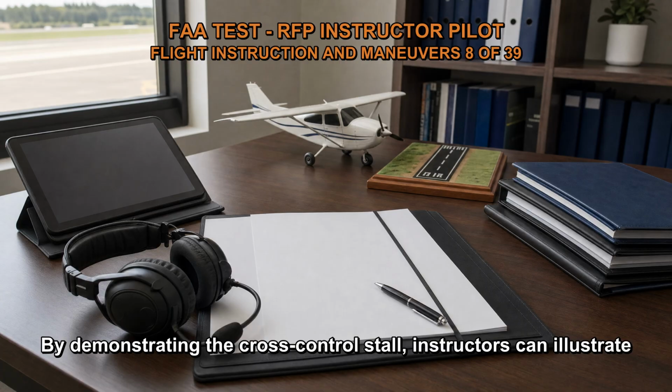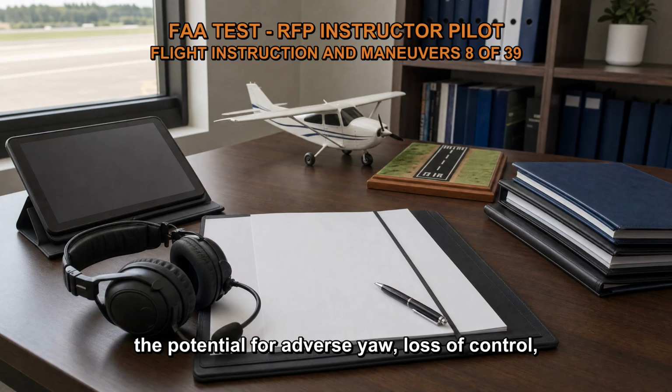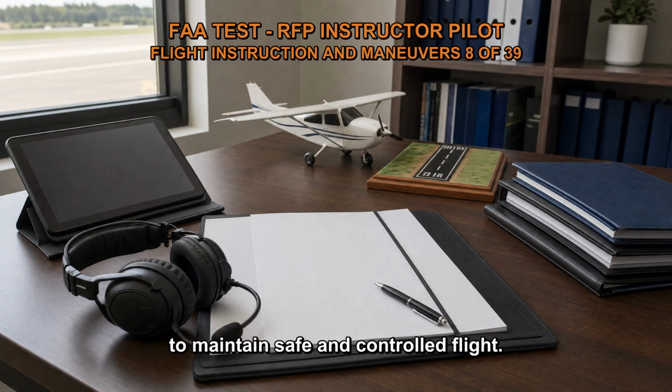By demonstrating the cross-control stall, instructors can illustrate the risks associated with improper control technique, including the potential for adverse yaw, loss of control, and increased stall/spin susceptibility. This serves as a valuable lesson in the significance of coordinated control inputs, especially during turns, to maintain safe and controlled flight.